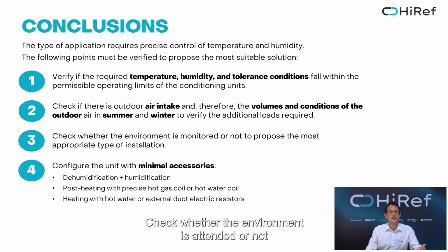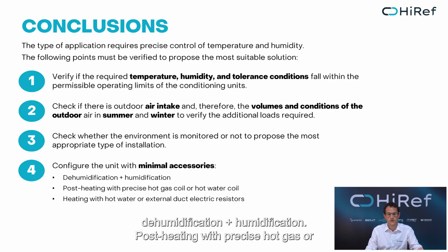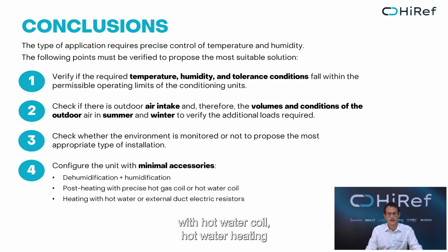Check whether the environment is attended or not to suggest the most appropriate type of installation. Configure the unit with minimum accessories, that is, dehumidification plus humidification, post-heating with a precise hot gas or with hot water coil, hot water heating, or external duct-mounted electrical heaters.